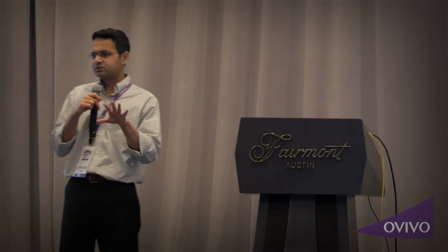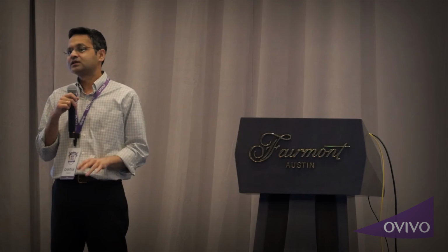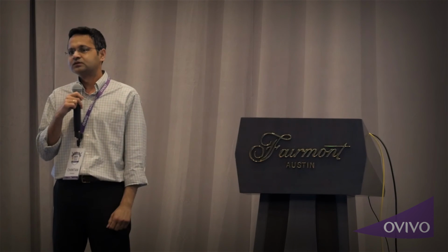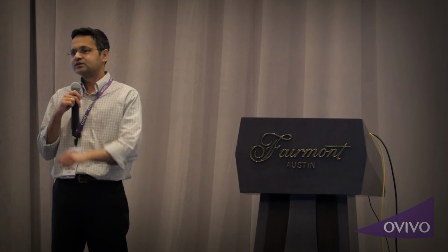We were monitoring effluent ammonia, effluent nitrates. Of course, there was DO and TSS monitoring. I think you saw it in a couple of slides, but we were monitoring the effluent ammonia and nitrates to be able to adjust the carbon dosing, alkalinity dosing, as well as oxygen control to get low TN.